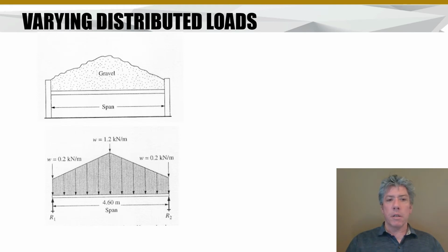You can put multiple loads together. Here's two varying distributed loads back to back, and we can model this as well. And this is about the most complicated it will get. In the real world you might vary it continuously changing, and there are integral equations for dealing with that, but we're interested in simpler things in this class.